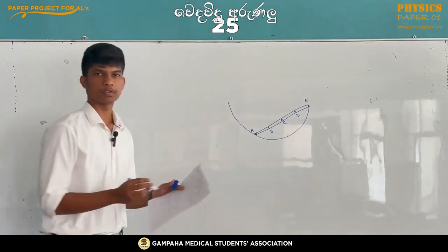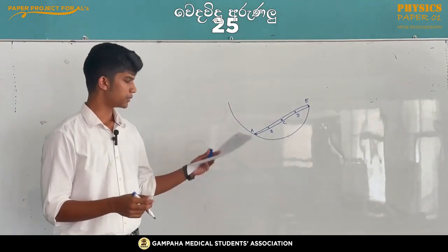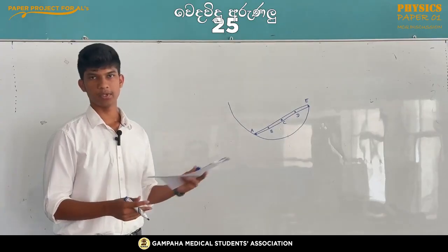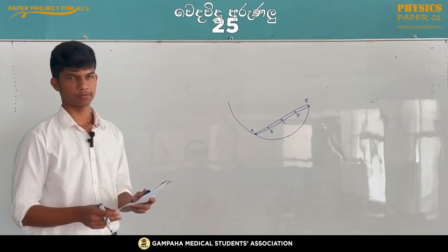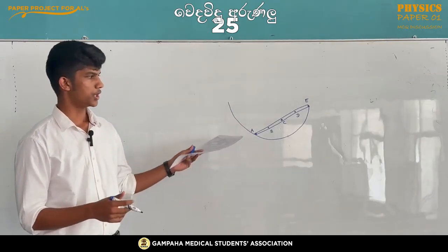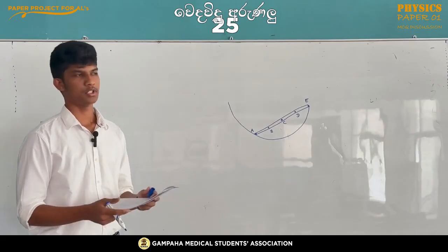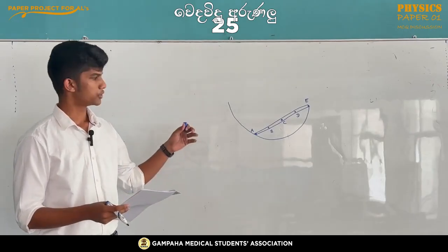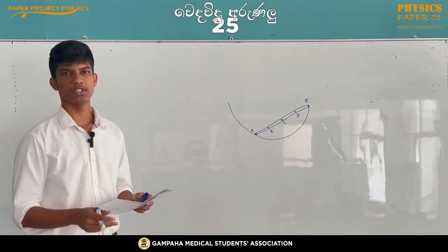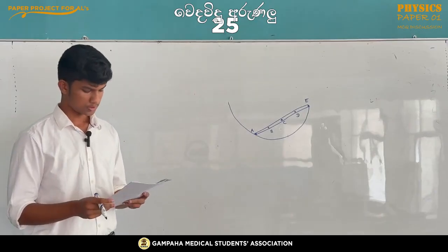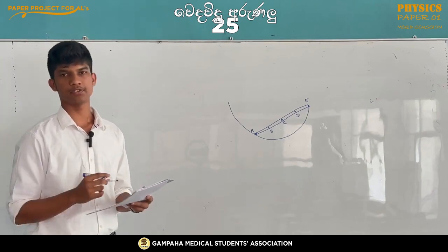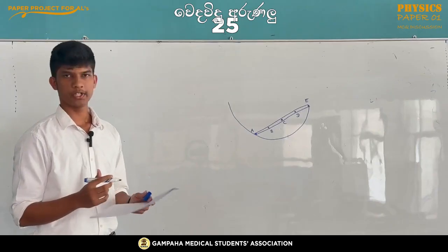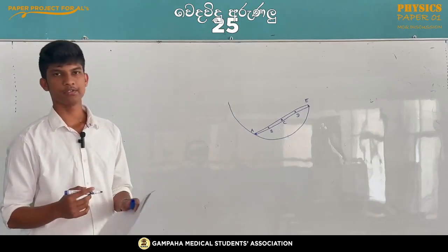So what you have to first realize is that the rod is in stable equilibrium, and also that the weight passes through the center of gravity. In a sense, since this is a non-uniform rod, the weight doesn't have to pass through the center of the rod. So once you draw two vectors, the normal reactions perpendicular to the rod, you will get the center of gravity.